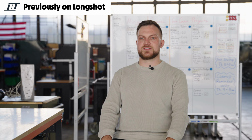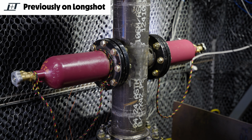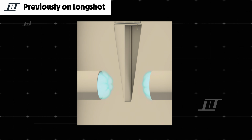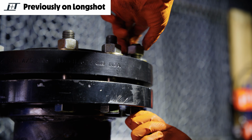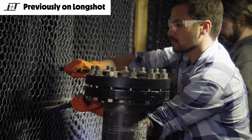The side injection test rig consists of a tube where the arrow wedge sits inside, and there are two pressure vessels mounted to the sides of that, so we can inject gas onto that wedge. In this particular case, this is all static, so we're not having that projectile be in motion. However, we can correlate this data to our simulation data to see how much force actually gets translated into thrust.